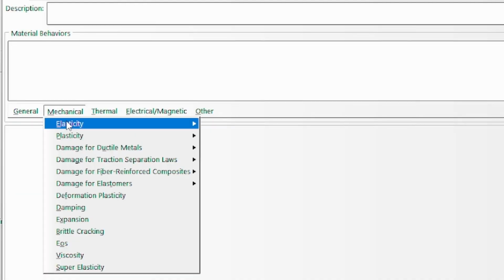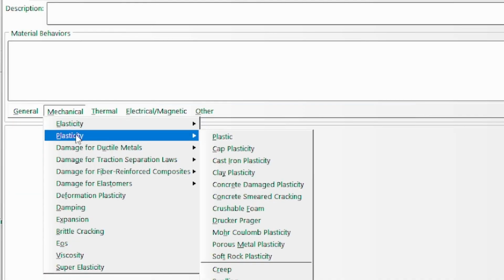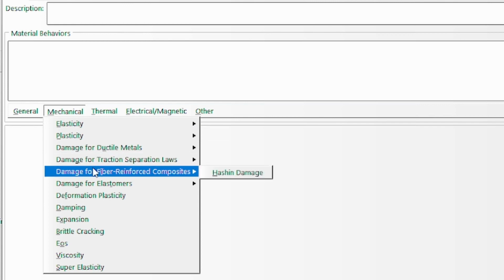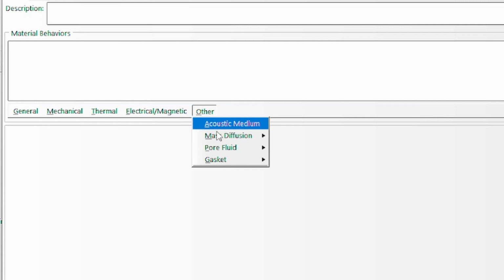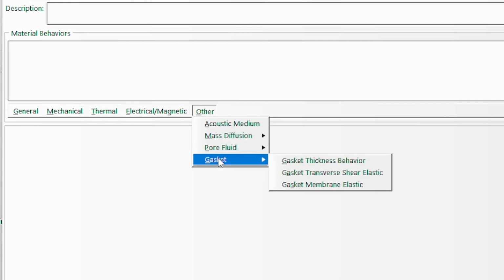However, in ABAQUS, there is nothing like that. What you have is the material models. So you've got elastoplasticity, you've got crystal plasticity, you've got damage, Johnson-Cook model, all that, and all the parameters are specified. It's now left for the user to find them for the different materials you're studying. So if you're studying steel, you need to find the properties that fit into that. And a lot of times when my students start using ABAQUS, they really struggle with that, because if you're working with SolidWorks or you're working with ANSYS, you don't really have this kind of problem. But with ABAQUS, you really have this problem.